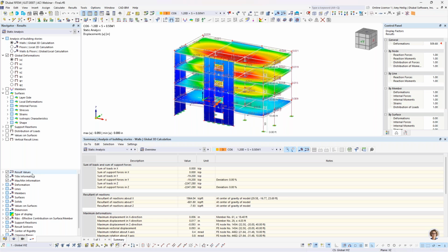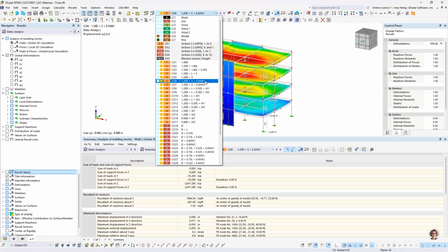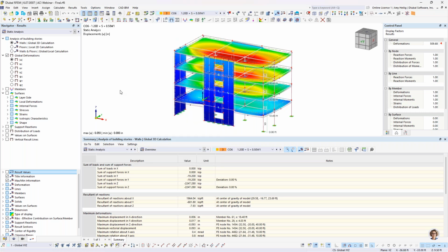And you'll notice that because I have defined that semi-rigid diaphragm, or if we had defined a rigid diaphragm, we have the additional settings up here under the static analysis results, including that 3D calculation. So again, we're calculating in a 3D environment, all elements are considered. We're running through all of these load combinations here, both gravity and lateral loads. We're just going to modify the diaphragm stiffness for this global calculation.